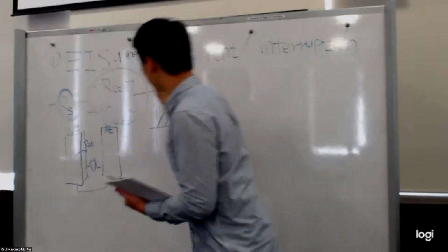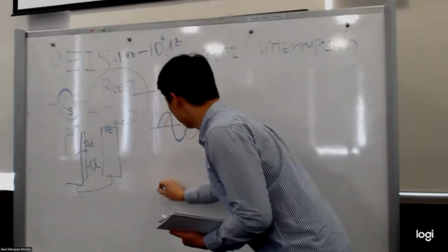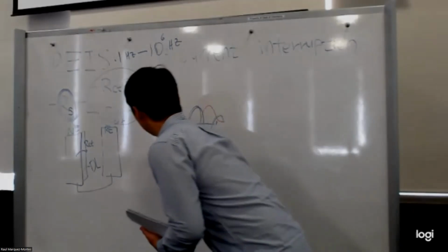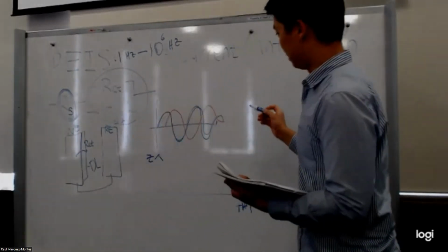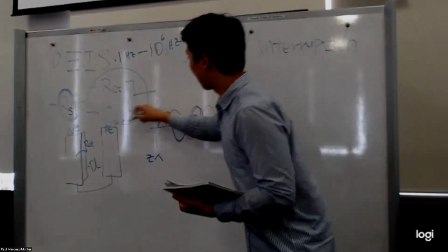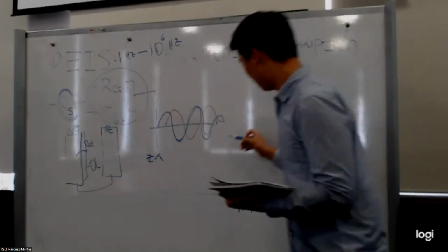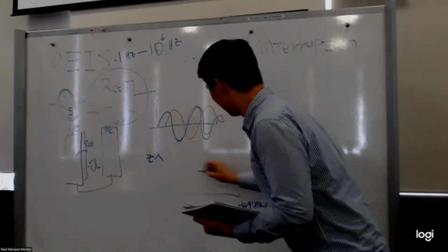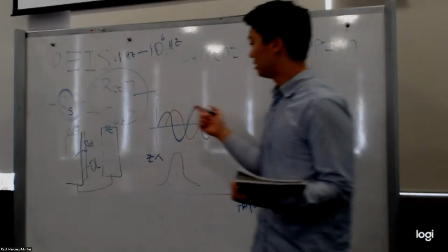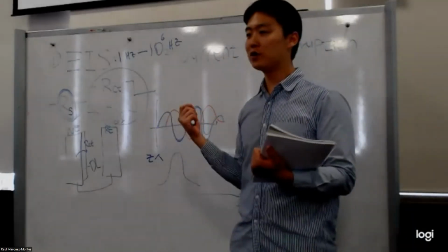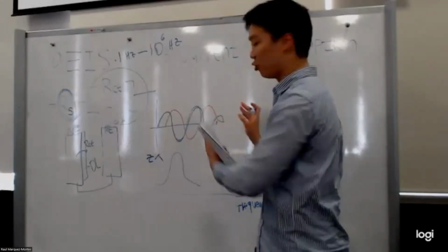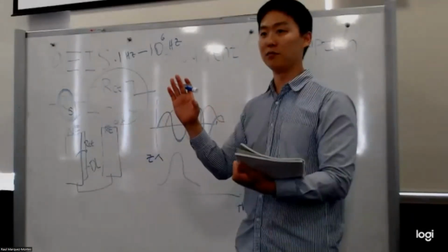So we can get the impedance signal according to the frequency range, and this RC circuit impedance signal shows up at the lower frequency region because, let's say, double layer charging, for example, always requires some time to respond to the applied voltage. So a phase shift occurs, which means there is an impedance term that exists.